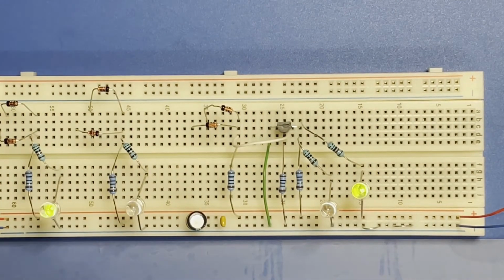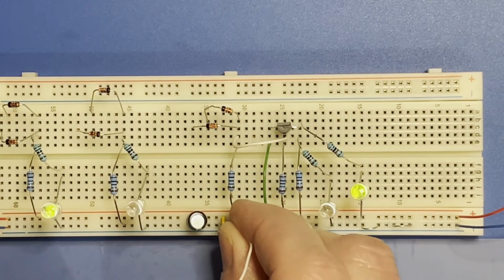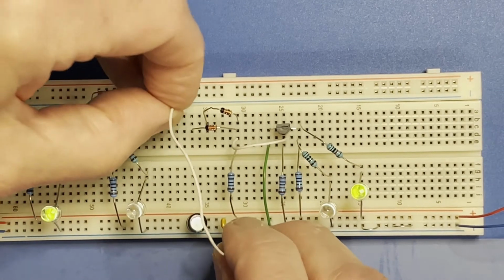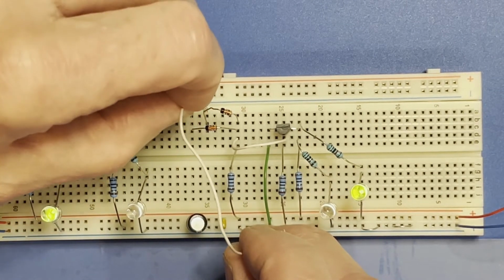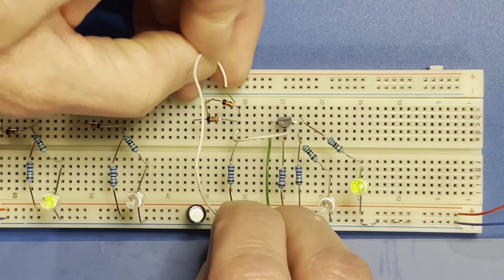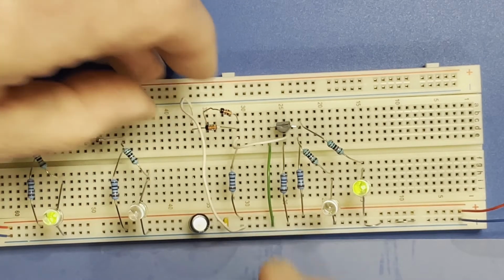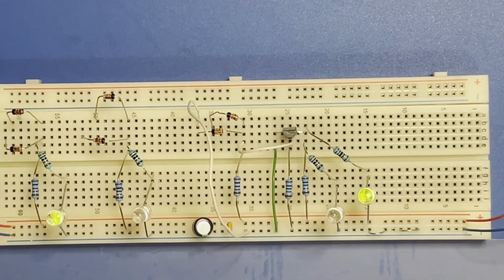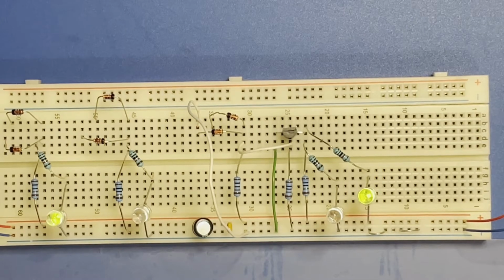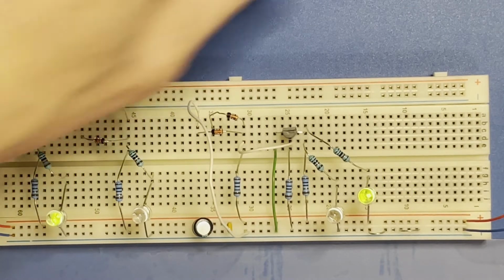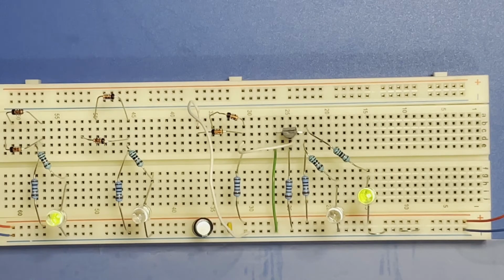Now the problem is this circuit will not work. If I ground directly one of those input diodes, nothing happens. Just to prove the transistor works, if I ground the other side of the diodes, so that's directly the base, it switches. But grounding the diode does nothing. And that's not even allowing for the fact that in a real-world circuit, the previous stage that connects to that probably wouldn't give exactly 0 volts output. There'd be some slight voltage drop across the transistor or whatever was controlling it or switching the output. So it doesn't work. And then people see these circuits on the internet and wonder what they're doing wrong. They're not doing anything wrong if they try to copy it, because the fundamental flaw is in the circuit.